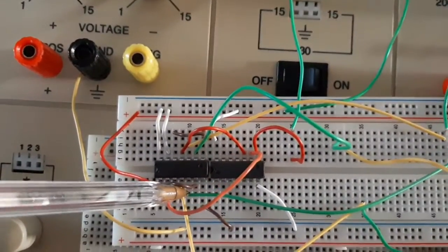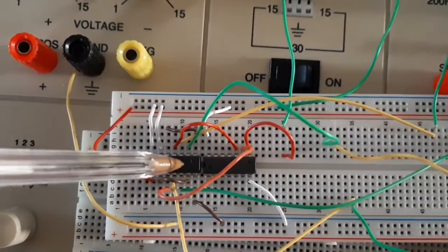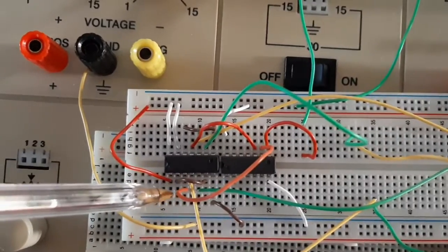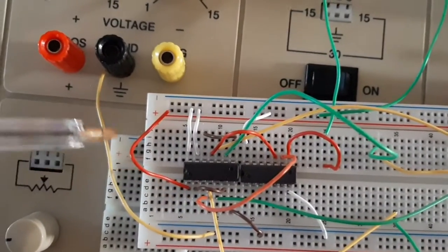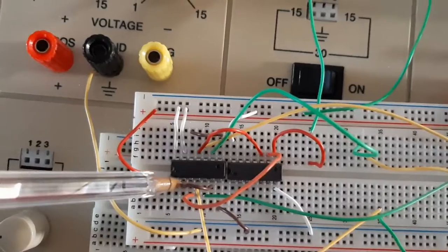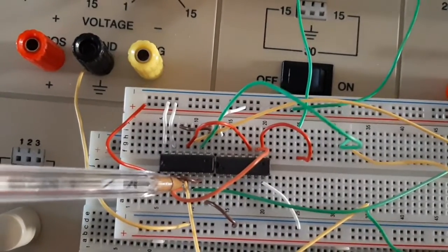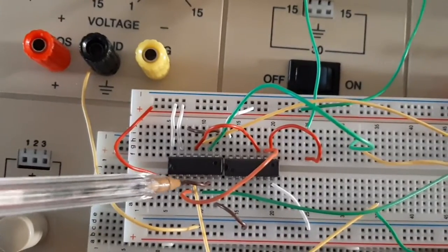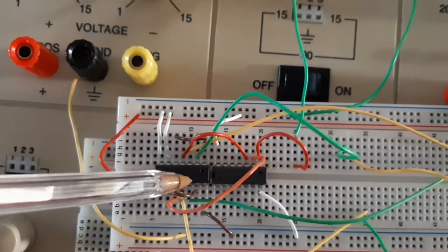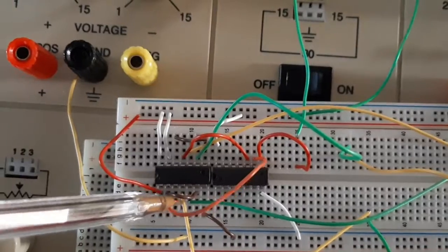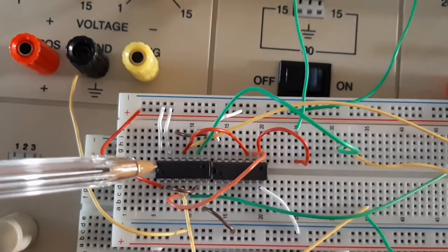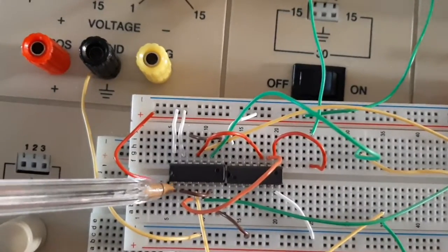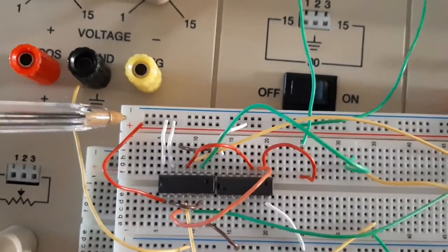In this XOR gate, which has A1 and B1, the output, which is pin number 6, which is right here, this brown wire, is connected yet again with a positive VCC. So pin 2 of this 7486 chip, which is its own exclusive OR gate, is the output of the other exclusive OR gate, which is comparing A1 and B1. And pin 1, which is input A of this second exclusive OR gate, is the positive VCC.